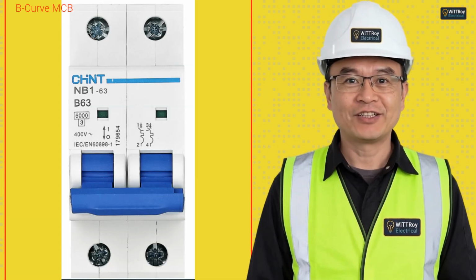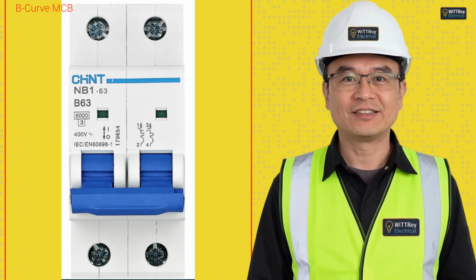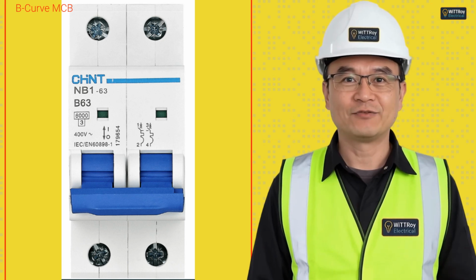Let's look at this device. First, I check the label. I can see B63. That means it is a B-curve 63 amp device. It is a 2-pole 400 volt B-curve 63 amp MCB.